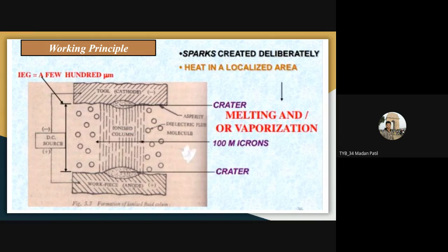Electrical energy we have used, so here we are calling the EDM process electrical-energy based. After passing that pulse, there is detachment of the electrons as well as the ions from the workpiece. Their kinetic energy will be converted into heat energy, and hence heating of the anode.